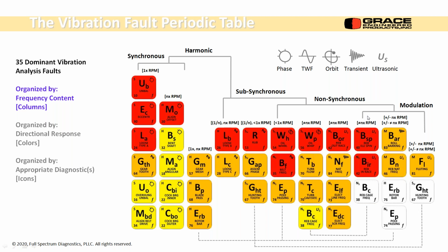If it's over here in a non-synchronous range, I might use an ultrasonic, a transient, or an oil orbit analysis to figure out the problem. So we're all working our way toward the root cause.